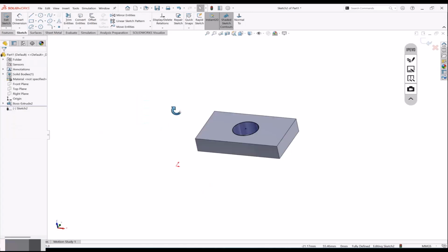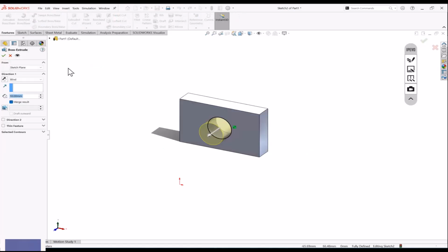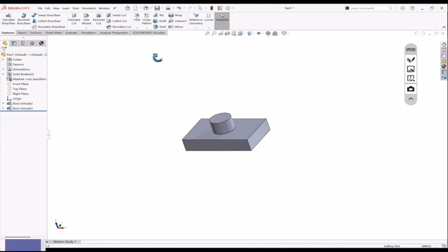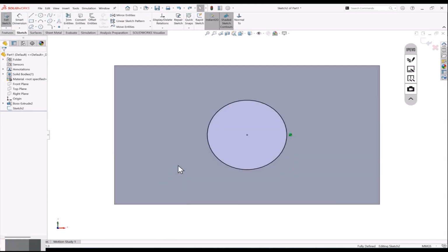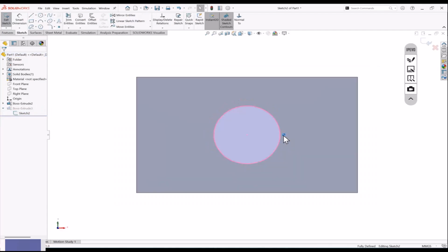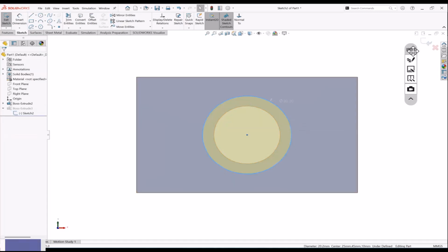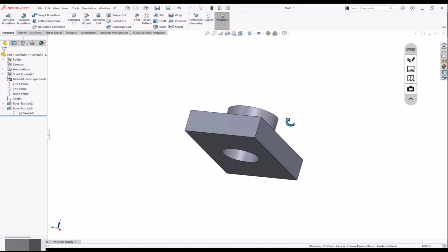You see here. Maybe now you want to use it for extruding purposes. You can extrude it here like this. Next, let's see, will it extrude even if the diameter is more than the hole? It will extrude, because there's no problem in extruding actually. We have told it the base is this face. So if I increase the size, that doesn't matter now. See?